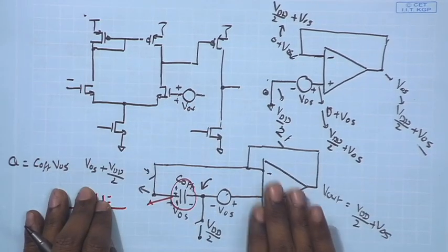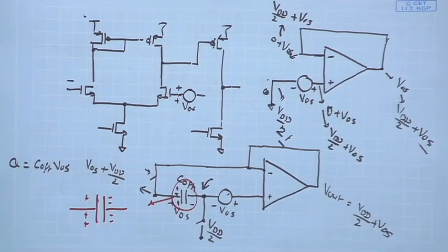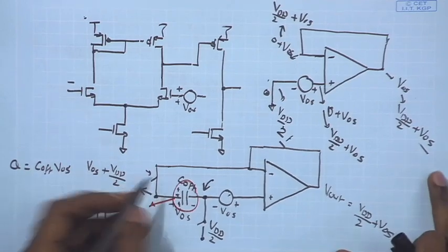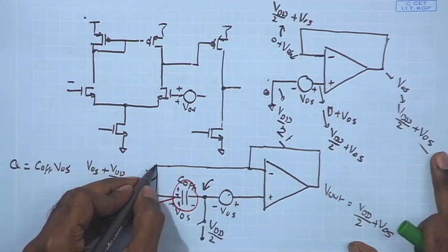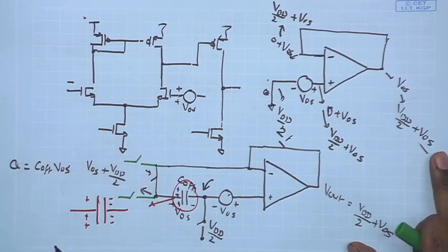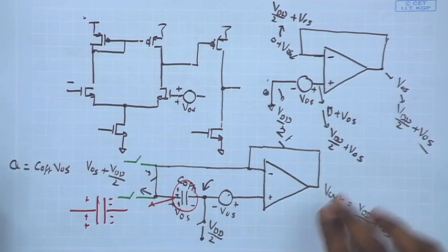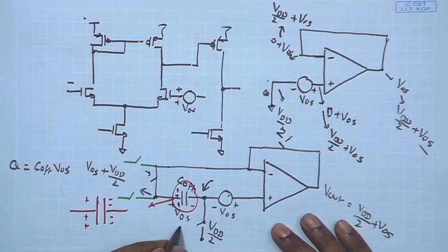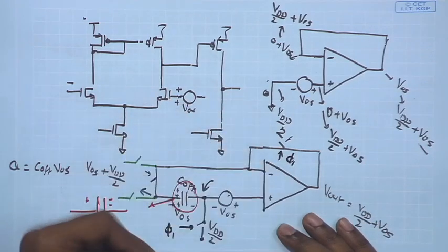So, now it has become an open loop amplifier, and then I can basically apply my inputs to the two terminals of the comparator through another switch. So, if I had these three switches getting on in phi 1 mode, if I call this say phi 1, which is one clock phase.